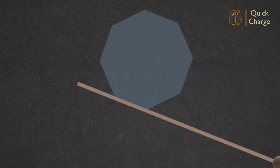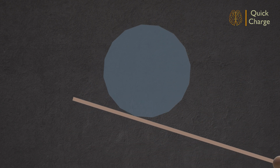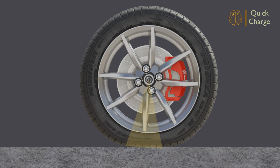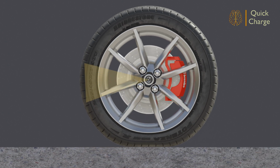With lesser and lesser dimensions of flat bottom, continuous tipping is happening at lower and lower angle. Isn't it similar to rolling? For perfect rigid bodies in contact, the dimension of the flat bottom is a measure of resistance to rolling. The static friction developed until tipping is contributing to the resistance. In the real world, actual rolling resistance is derived from various factors. Let us discuss the same in another video.